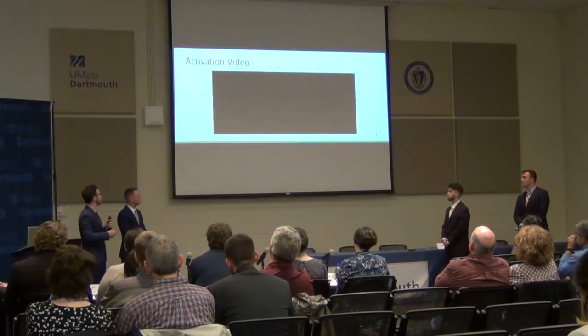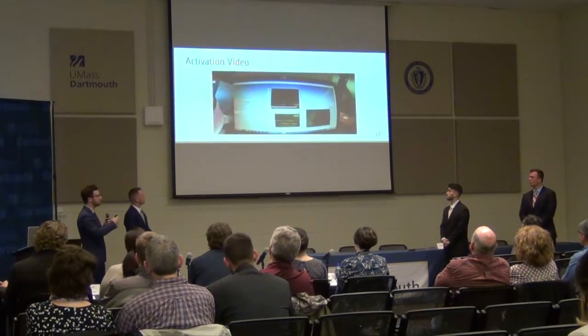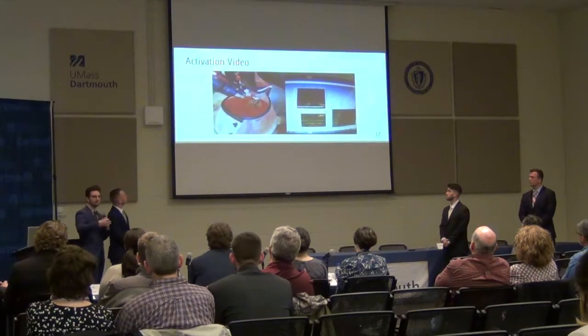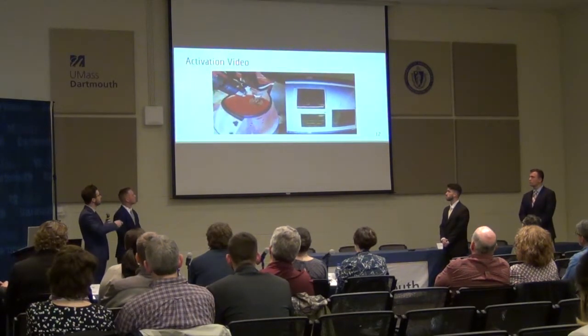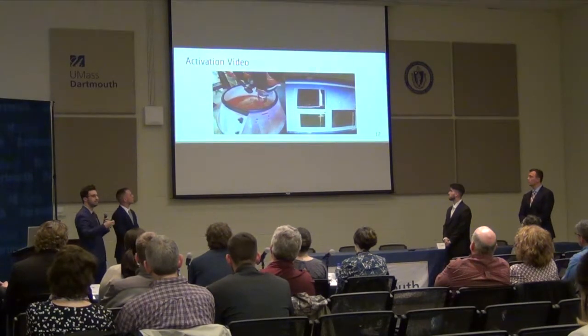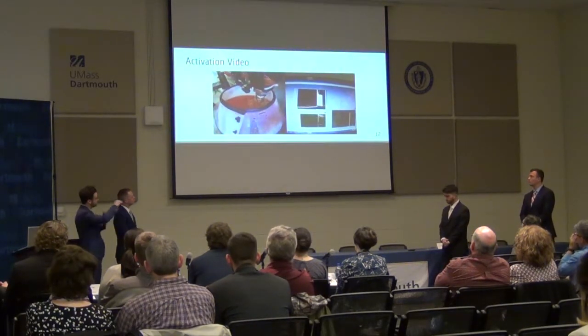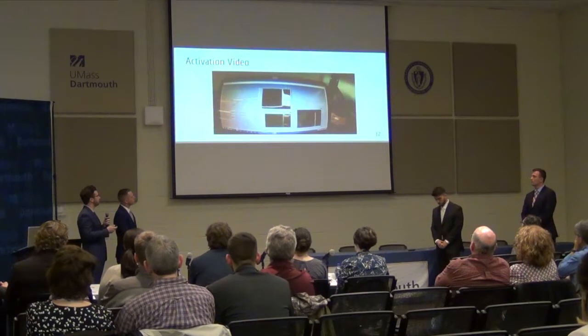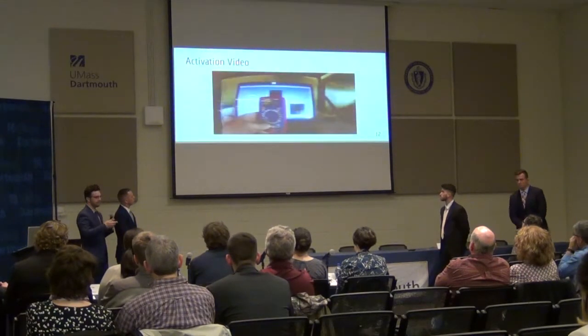Here we have a video of a wet test. On the left, you're going to see a sprinkler activate. Water's going to come through, and the light will shine. And on the right, when that happens, you're going to see that spike in voltage, and just below that spike up in frequency. And as you can see, we have that step function that indicates an activation.